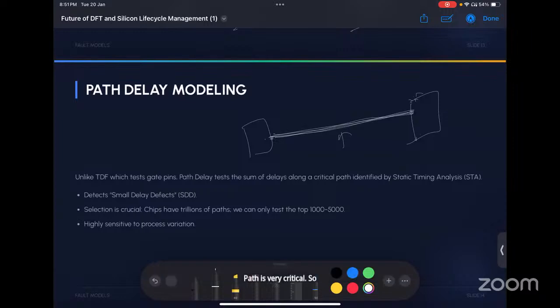First we have seen stuck-at zero fault and stuck-at one fault. Next one is transition delay. Let's say there are no transition delay faults. Now the next part is path delay. From one node to another node, data should not get lost because of the wire delay. So there's a different kind of faults: path delay faults.